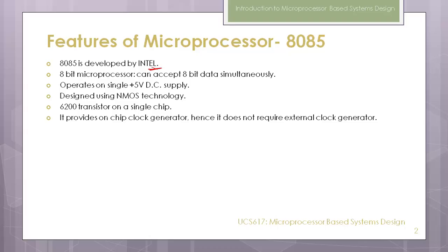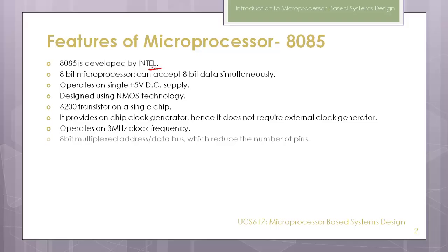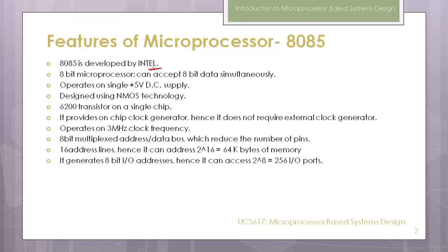It provides an on-chip clock generator, hence it does not require any external clock generator. It operates on a 3 MHz clock frequency and has an 8-bit multiplexed address or data bus, which reduces the number of pins. Now 16 address lines are there, hence we can address 2 power 16, means 64K bytes of memory. It generates 8-bit input output addresses, hence it can access 2 raised to power 8, that is 256 input output ports.